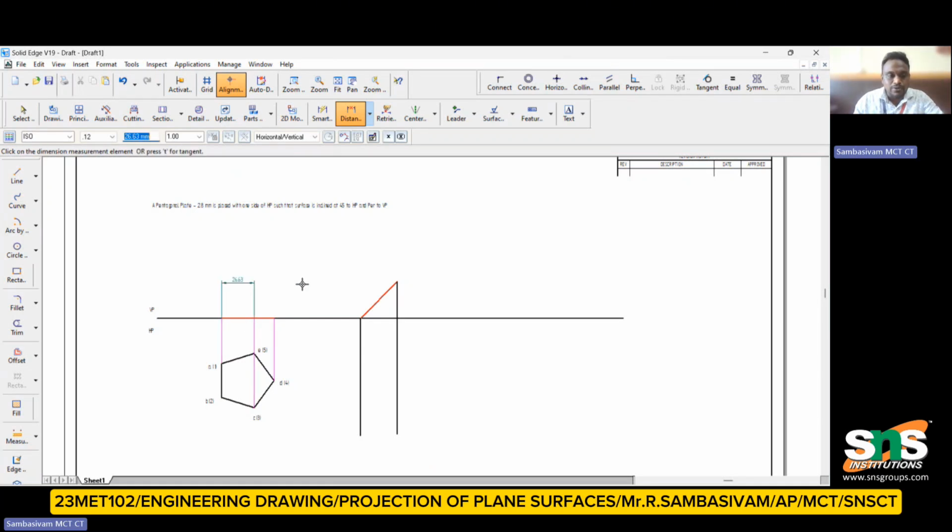So the distance is 26.23. From this point, I am going to draw this 26.23 at an angle of 45 degrees, so that I can match the plane. From this point, I'm going to draw a perpendicular line. So it is also representing this one.